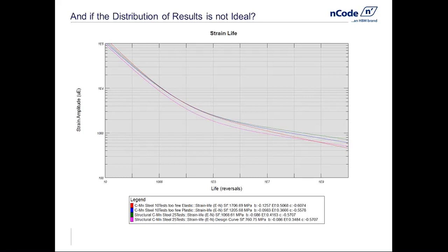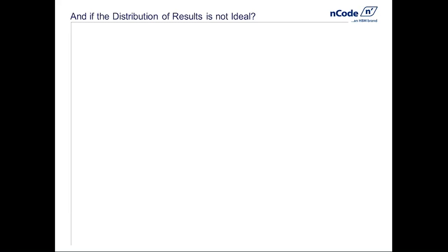In fact, the red curve crosses the design line. But on the whole, the design line is beneath, I will say at that point, having said that, but it crosses the curve well above 1e8 cycles with the reversals, which is a very, very long life anyway. But I can demonstrate this again by the simple reason of using the GlyphWorks analysis routine.